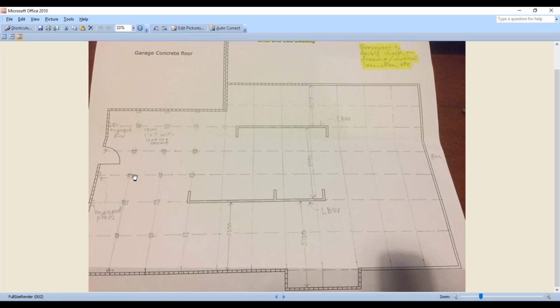Okay, yep. Because if you look at your Australian standard, and I've closed it down, but in the Australian standard, when it shows the joists underneath our load-bearing walls, you normally see there are 2 joists there. So that's why people quite often add 2. All right. Okay. Thank you.